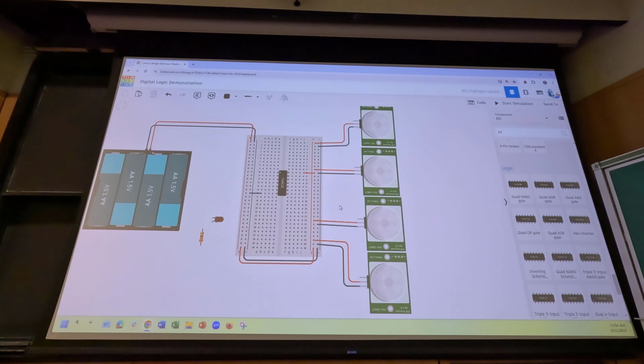Seeing a lot of people with sensors on the screen, but not necessarily a lot of signal wires going anywhere. Think about the sensor signal pin as an output that will be low by default and go high when it detects motion. Think about where you would want that to go with an OR gate.